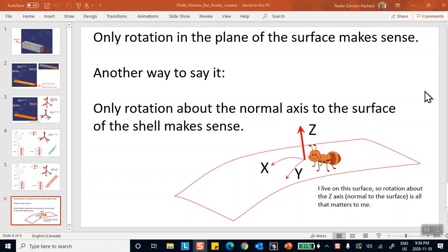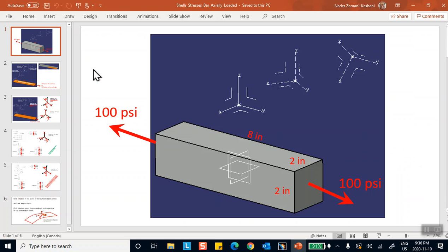In order to do that, I have to set the stage for things that are not quite well documented in CATIA, and those are plotting stresses. I did the solids first, and now we're going to be doing the shells. This is more pertinent to composites because a composite is made of a stack of plies or laminas, and the direction of the fiber in each of these is different, and therefore we may want to plot the stresses using different coordinate systems.